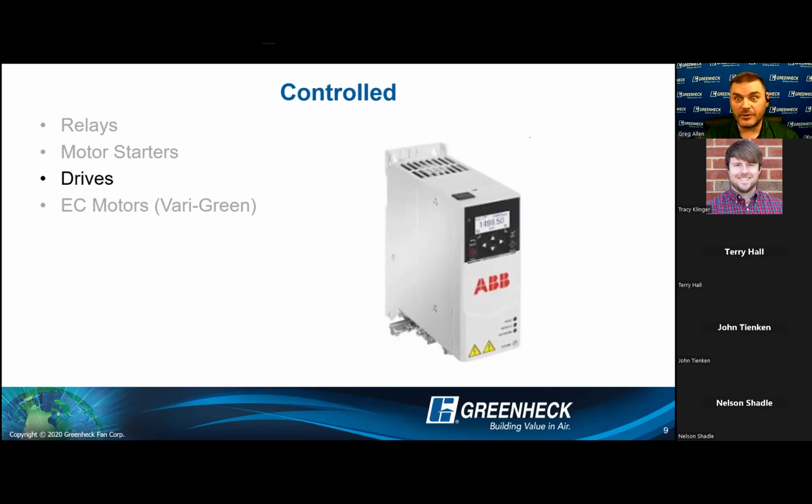Also, on some drives, you can flip what kind of modulating input it's expecting. And you can say, hey, I want to send you a 4 to 20 milliamp signal. All right, so now it's going to accept that as both a run and a speed reference.